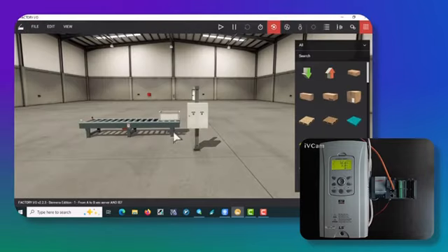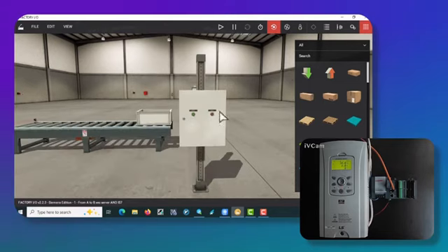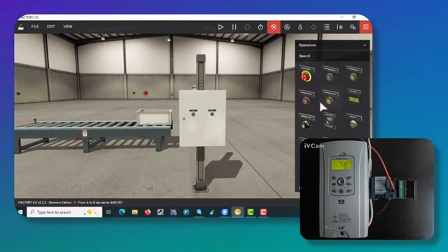I've selected a project, a conveyor that carries an object. But if you want to bring in the push buttons that are on the panel, or place the panel box itself, from this section you select the operator option. You'll see that there are all kinds of push buttons, emergency stops, 2-position switches, potentiometers, even panel boxes and panel stands. Whatever you need, you can choose from here. Here I selected a panel stand. I brought in a type of box, a start push button and a stop push button. The start button is for running the conveyor and the stop button is for stopping the conveyor.